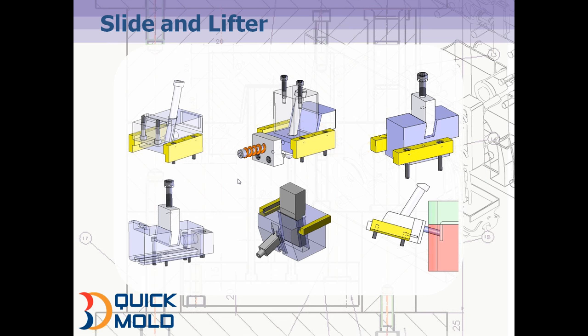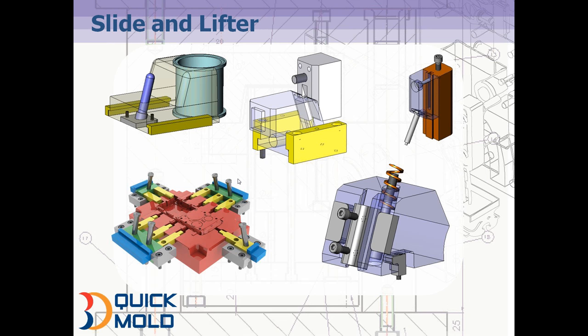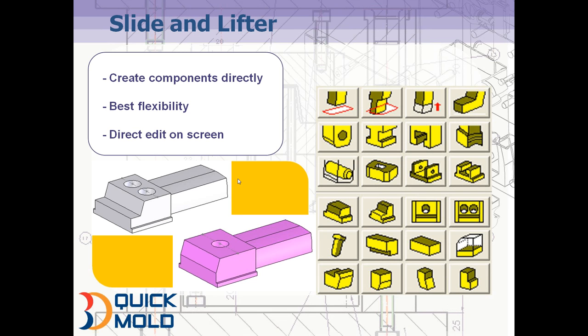I'll continue with a few more things, like the slider wizard. The slider wizard helps users simplify and standardize slide and lifter design. There are some examples you can view in these slides, which are already built into this library. It offers intelligent slide creation with minimum inputs, so the user need not spend more time on this. It allows the user to edit all the parameters directly on the screen, and easily release undercuts with adaptable lifters and slide mechanisms. You can view the library item in these slides.